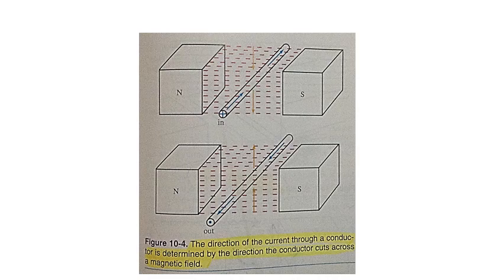The strength of the induced voltage in a rotating coil depends on two things: the number of magnetic lines of force cut by the coil, and the speed at which the conductor moves through the field. When a single conductor cuts across 100 million, or 10 to the 8th, magnetic lines in 1 second, 1 volt of electrical pressure is produced.